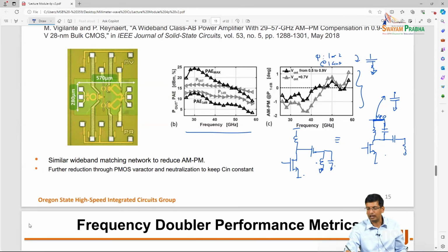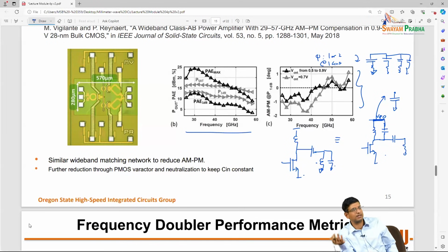But now, in order to still get good bypass, you'd make an array of them. So the supply basically looks bypassed by an array of detuned capacitors. You don't want to put a high Q capacitor on the supply node in general. That's usually the proximate cause of most problems with PAs, right?